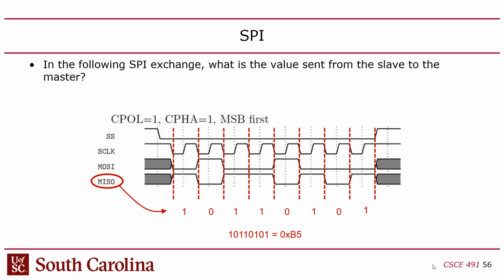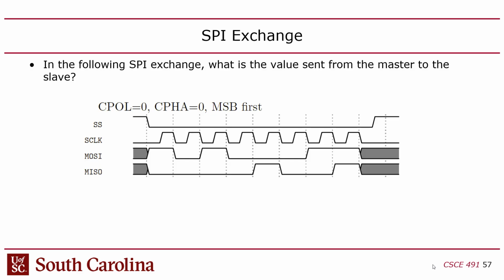Okay, and again, SPI is always in multiples of 8 cycles because they're 8-bit words. It doesn't have to be 8, but it has to be a multiple of 8. Or, well, I shouldn't even say that, because technically you could abort an SPI transfer if the master just sends slave select high. But I'm not sure if that's advisable. It might confuse your peripheral.